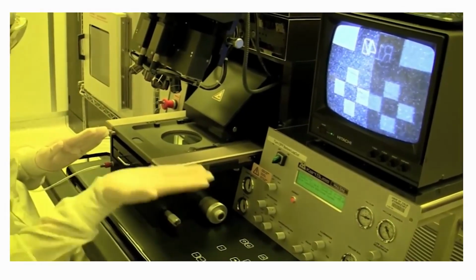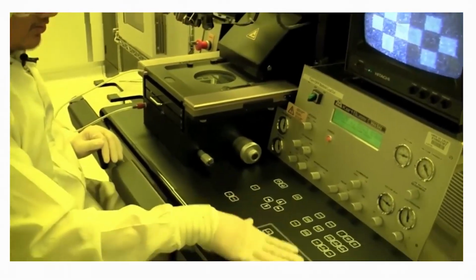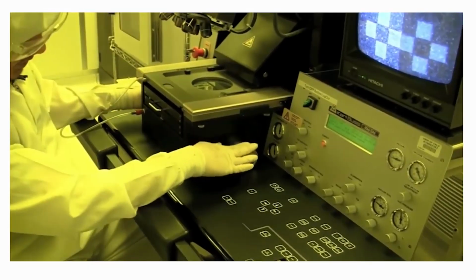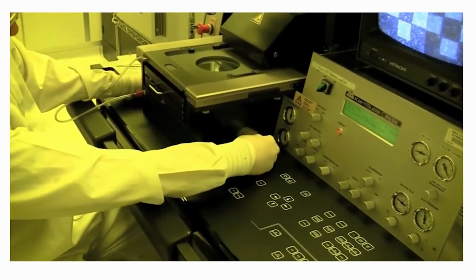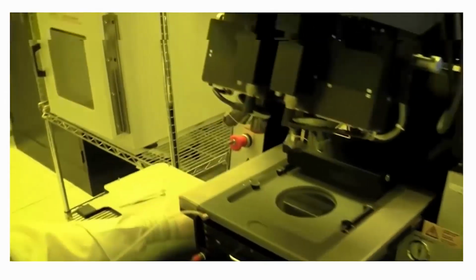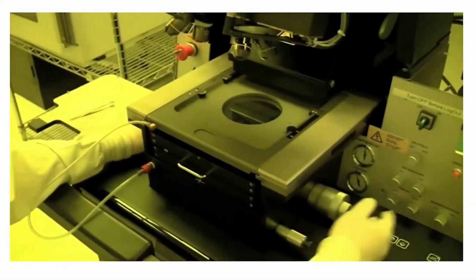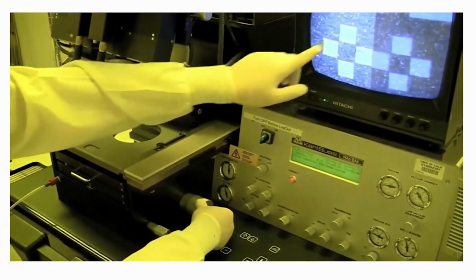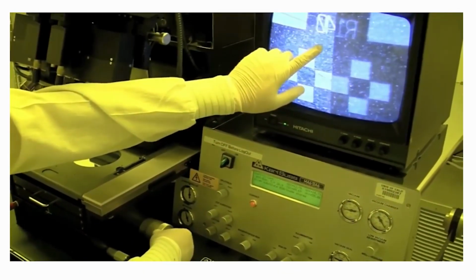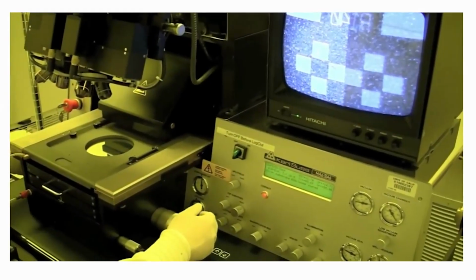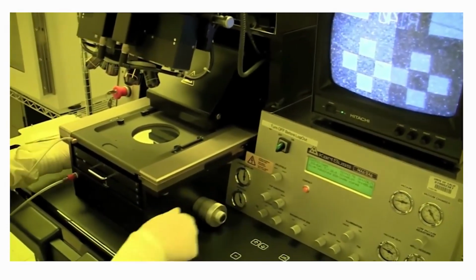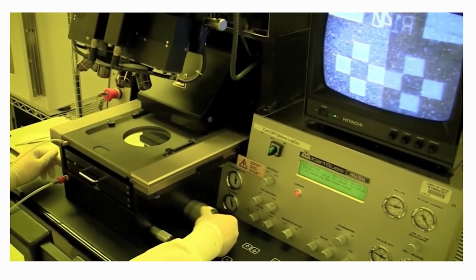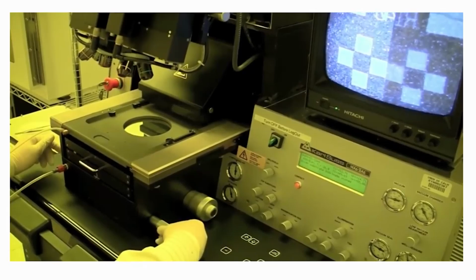So how do you move the wafer? We know that these buttons move the microscope. So how do we move the wafer? It's these knobs right here. This is the Y. The X is on this side, and this is the tilt. So I'll give you an example. I can turn this, and you can see the background, these images moving. And then you can see this moving. So this is the Y position on the left side, and on the right side is the X knob. And you can adjust the tilt with this too.